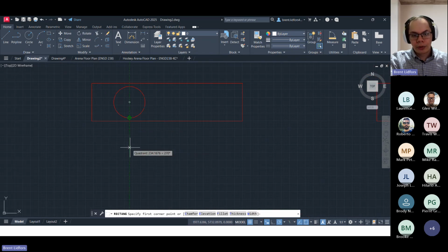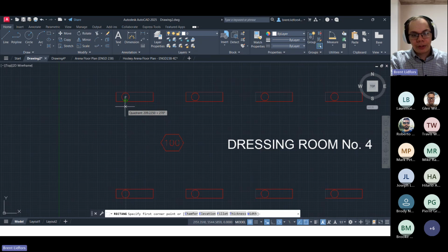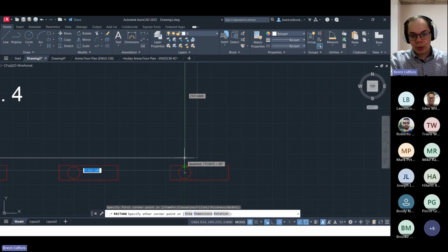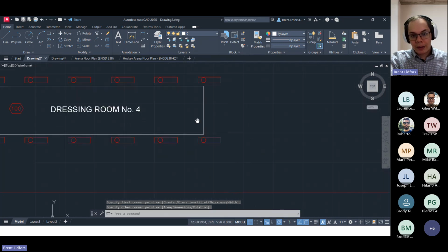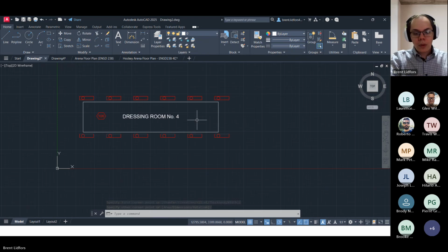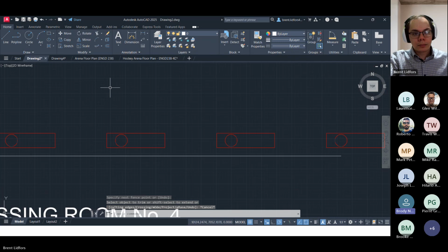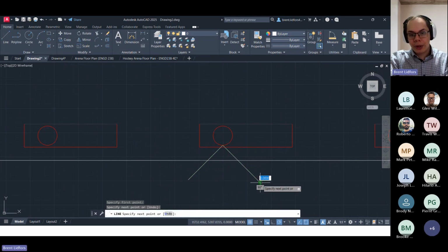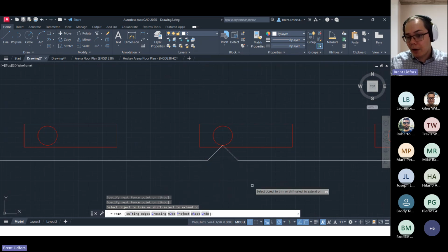So the quadrants of the circles. I could use that snap, draw my rectangle, find the quadrant snap of this luminaire, form that rectangle there, and that's the basis of my conduit. All I have to do now is trim out this side and make those little V shapes. I can simply take this quadrant, use my polar tracking to make a couple 45-degree lines that pass through it, then trim out the excess, and there I have my first triangle or V shape.